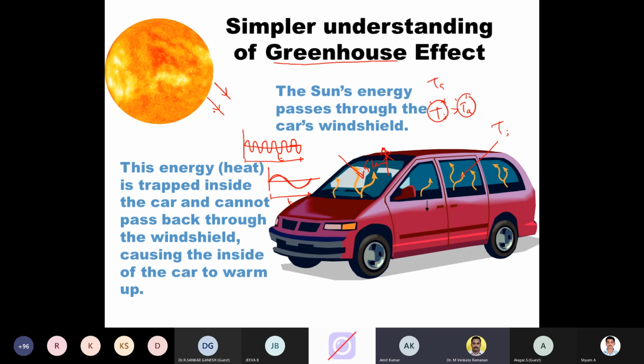Yeah, okay. Now, the rays, whatever we have from the sun, especially the beam radiations, will be of shorter wavelength. It has the energy, it will be able to go through this glass. It hits the interiors of the car, it will be losing its energy. Transformation happens. As a result, the short wave will become long wave. The long wave will never have the energy to overcome the glass, hence it will be re-reflected back. As a result, the interiors of the car will become warmer.